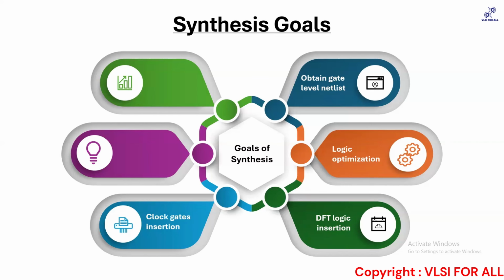So I can turn off this flop for 6 cycles. Otherwise, 6 times your clock will be toggling. And the main intention of a flop is that every time the clock toggles, it keeps on passing the input. But as a designer, we knew that for at least 6 clock cycles my input will remain stable at 1. Then why am I making the flop toggle?